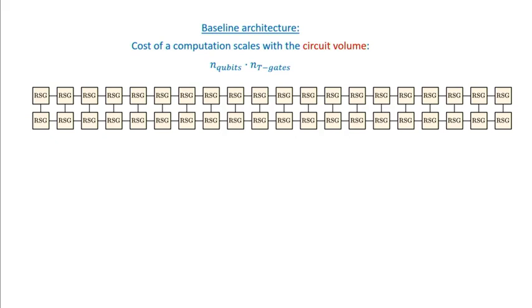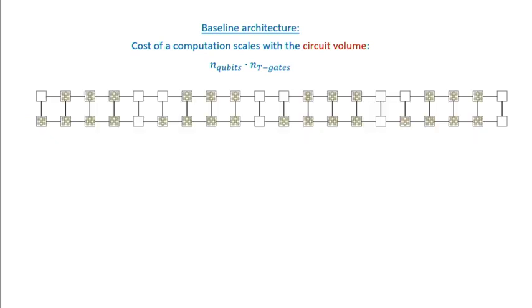Because connections between the different modules in a photonic quantum computer are implemented via macroscopic fiber optic links, you don't necessarily need to connect them up in a square grid like that. You could connect the modules in a network without any locality constraints. In addition to that, photons routinely need to go through switches that select their destination. So we can use fiber links and switches to not only establish connections between faraway modules, but also have switchable connections. The neighbors of each patch can not only be far away, but you can also have a much larger pool of potential neighbors available.